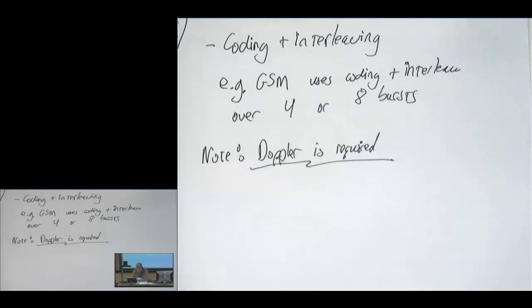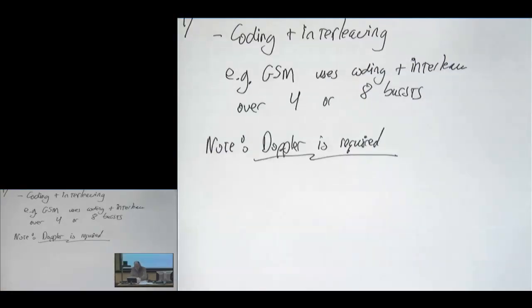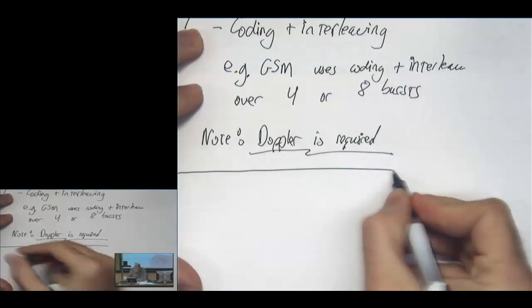So actually even 120 milliseconds is long. So you have to have a fair amount of variation in the channel. So this concept doesn't work in some systems. It works in some, but not others. In cellular, this would work if you're traveling by car or bus or train, but maybe not at pedestrian speeds. So time diversity is good, it works, but it's not always there. So let's look at some other techniques here. This is commonly used, but it's not always available. So another approach is frequency diversity.